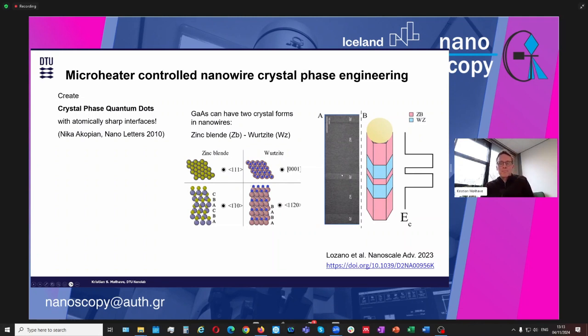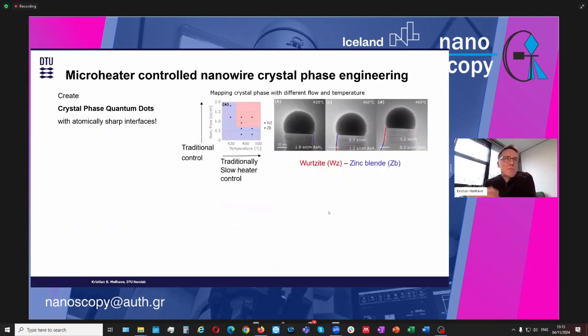possible today. So in the old days, you would make quantum dots, say, by changing from gallium arsenide to indium arsenide, and that means changing gases, and that takes time to change, and then you will grow a boundary that's very extensive, and you've got a diffuse boundary. But with a phase change, you can make sharp boundaries.